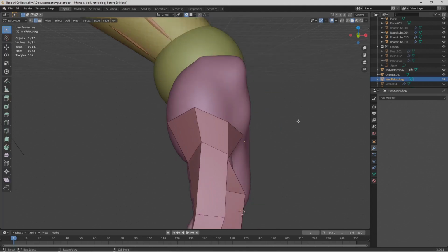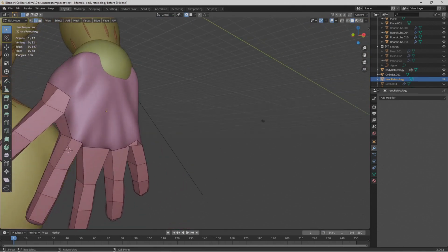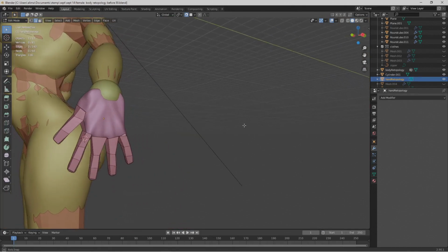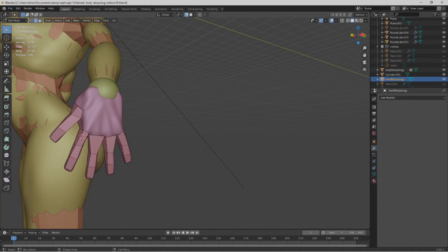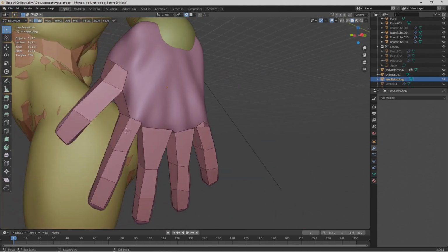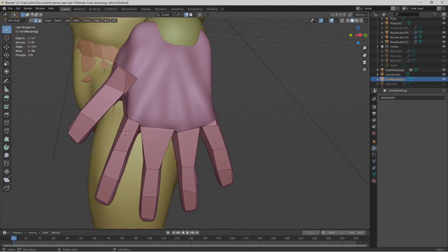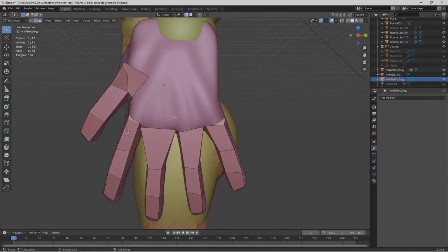Okay, what we're going to do now is zoom back, hold the mouse button to rotate the view. I'm going to hold Shift, press B to draw a zoom box. Zoom in, hold the mouse button to rotate. I'll select a piece of geometry so I can rotate off of that geometry. I'm going to select this edge here, hold the mouse button to rotate, hold Control, then left click, wrong. Left click here, hold Control, that edge, there we go. I'm letting go of Control.